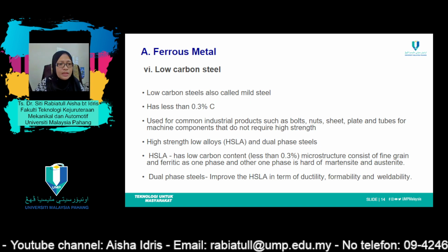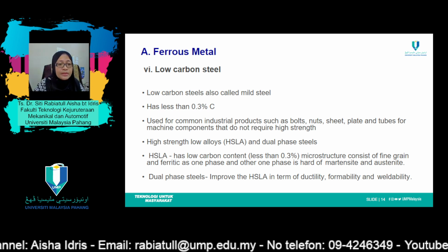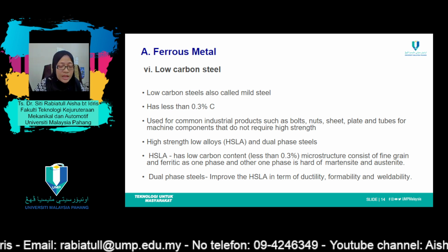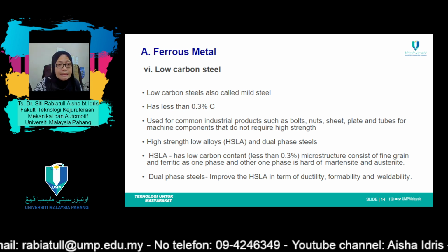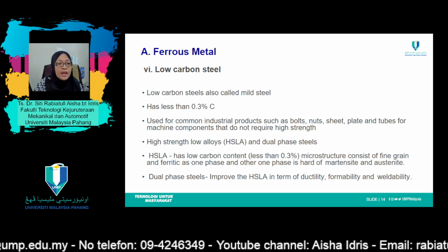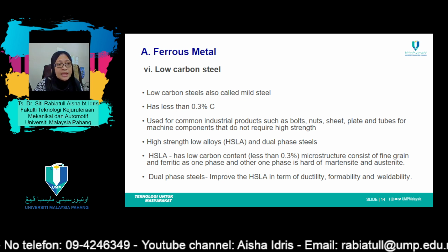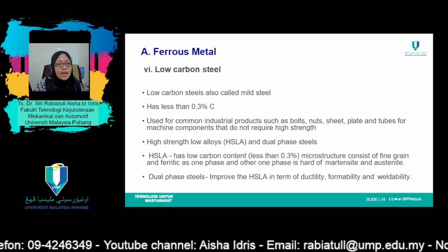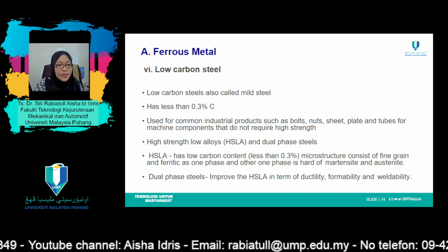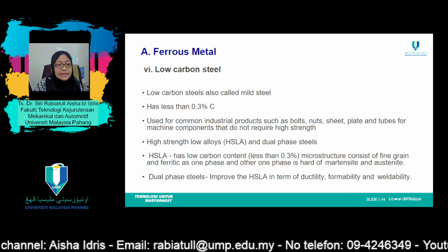For low carbon steel, of all the different steels, those produced in the greatest quantities fall within the low carbon classification. These generally contain less than about 0.25% carbon and are unresponsive to heat treatments intended to form martensite. Strengthening is accomplished by cold work. The microstructure consists of ferrite and pearlite constituents. As a consequence, these alloys are relatively soft and weak but have outstanding ductility and toughness.